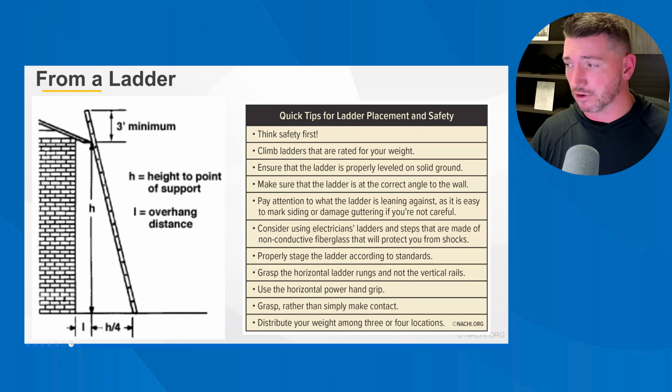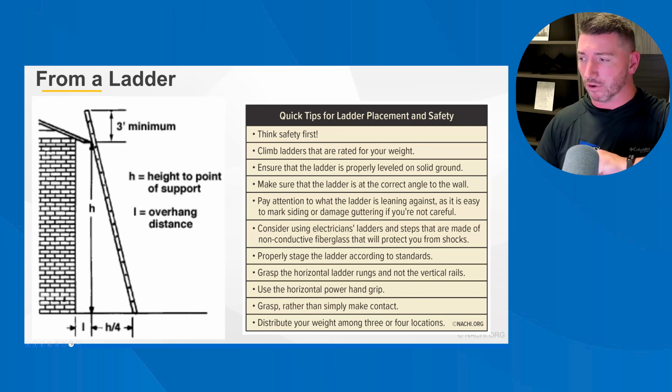Make sure that the ladder's at the correct angle to the wall, the 4-on-1 rule. Pay attention to what the ladder is leaning against, as it's easy to mark siding or damage guttering if you're not careful.